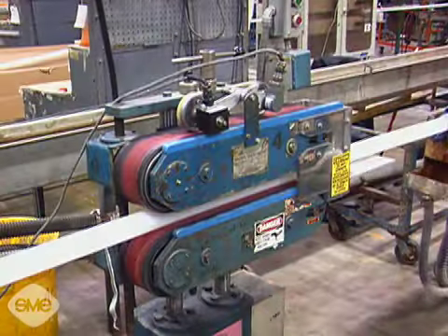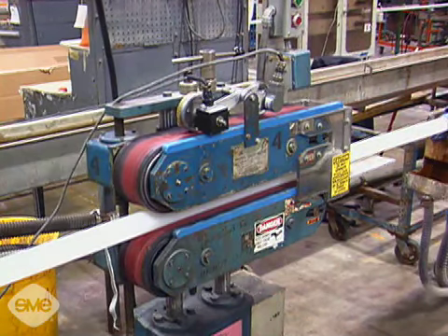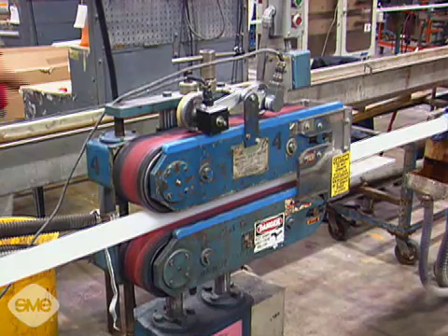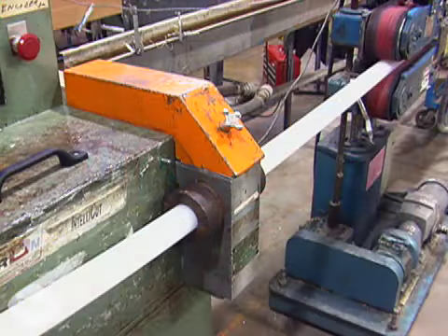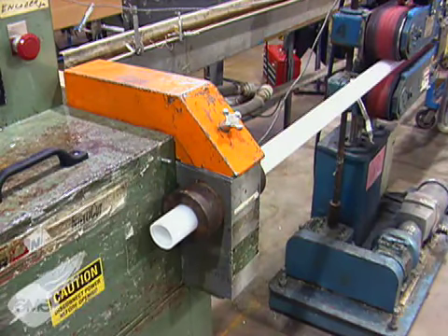This water cools and solidifies the extruded plastic as it exits the die. At the end of the cooling tank, haul-off rolls pull the profile away from the die at a uniform, controlled speed. As the profile is pulled through the haul-off rolls, a cutter shears it to the required length for further processing.